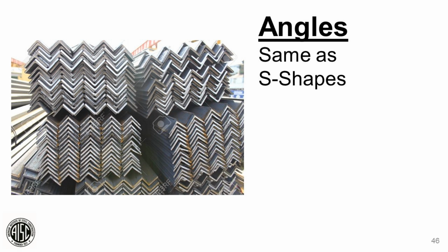What's presently in the Steel Construction Manual is 36 ksi material. It doesn't mean that 50 ksi material is not available, and you can do your connection designs or any designs with 50 ksi material. Obviously if you have dual certified material, which means you may have material that meets A36 and A572 Grade 50, you can use 50 ksi for your designs. That is almost the same as what we talked about with HSS shapes, where A500 Grade B/C, you may get an angle where the mill test report says A36 and also says it meets A572 Grade 50.